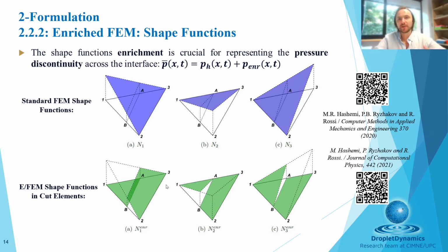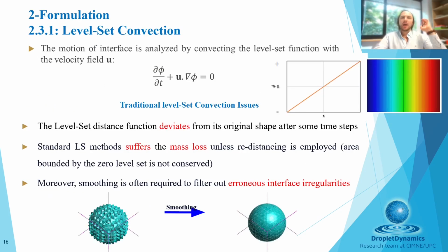That's why we call our method an enriched finite element method and not extended finite element method, because we actually condense these functions. So finally, when we assemble our total system of equations, we don't have any additional degrees of freedom. So we represent the discontinuity, we add the contributions corresponding to these additional shape functions, and then we condense them. Okay, and this works pretty fine.